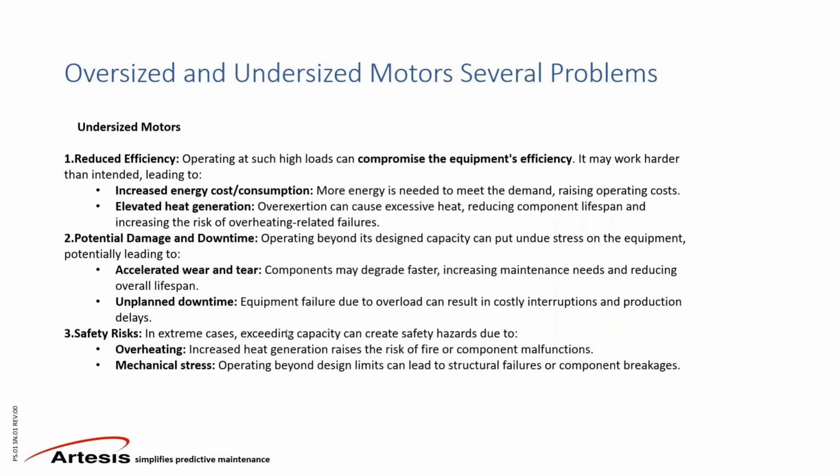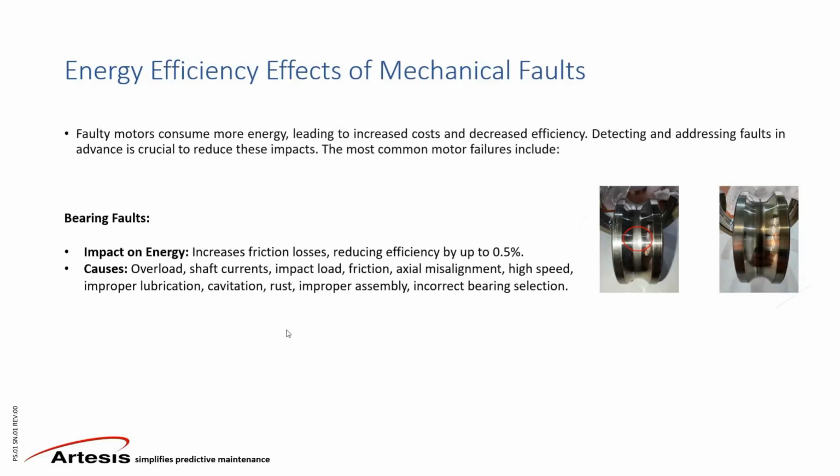So we have to keep a close eye on the motor's load levels, and make sure that overload situations are under control and don't happen. If that is an ongoing thing, you have to consider a properly sized new motor for that particular job.